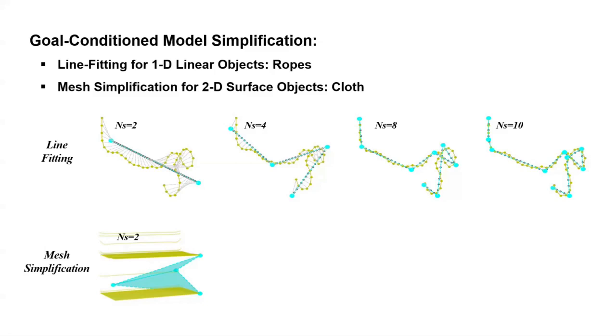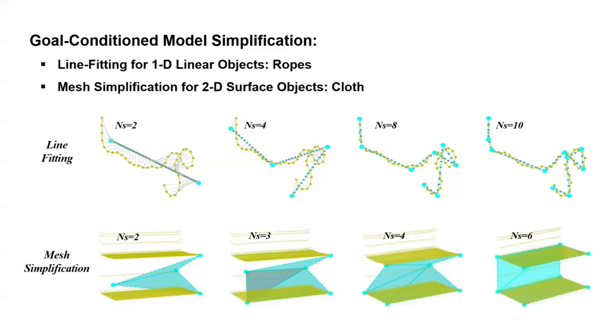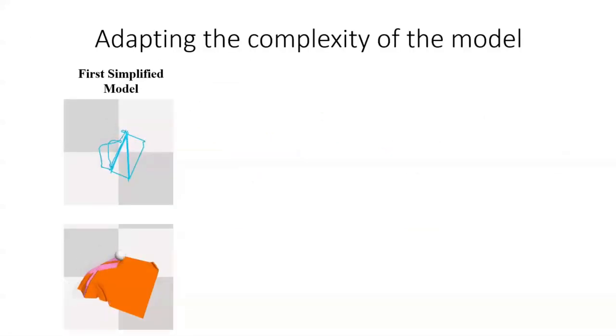Yeah. So then we fit triangular models, trimeshes, to that. Here we use two triangles to fit. We check if it's a good fit. If it is not, we increase detail, increase detail, increase detail until we have a good fit to it. Then this becomes our model, and we extract a dynamic model from that. So if we have a task like folding the towel into two, we extract a certain simplified model. This is the model for this one, and we run the planner on this.